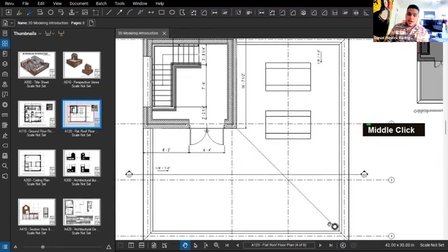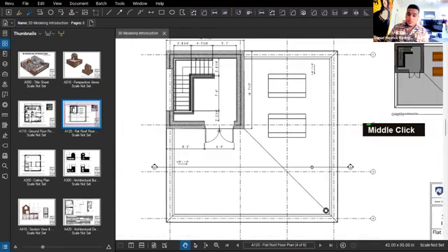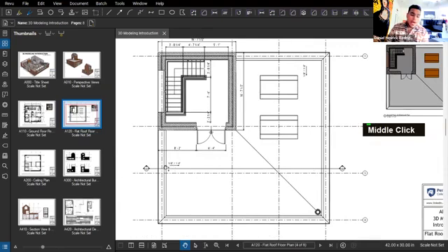And we do have a drain here. The drain is a great context clue for you to understand what's going on. So we have the 2 arrows, and they're showing that the roof goes towards the middle here, right? So our slope is gonna be, we have 2 options really. We have this line, the middle line or the exterior line.